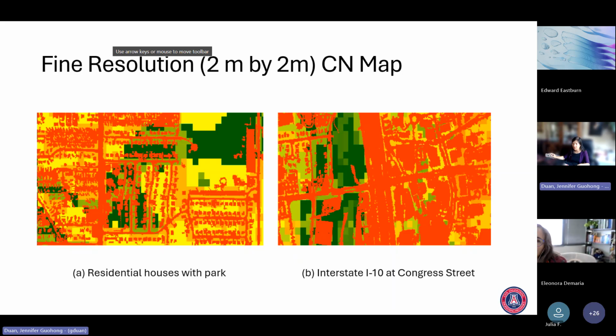If there is no water in the pond, the water is going to fall into the pond, fill the pond until it is full, and then when it's full, the water is going to become runoff. Okay, but in natural water, like a lake, the lake's curve number is 100, because the lake water directly becomes surface runoff. So they assign 100 to lake water bodies. Same thing if you have a pond in your backyard.